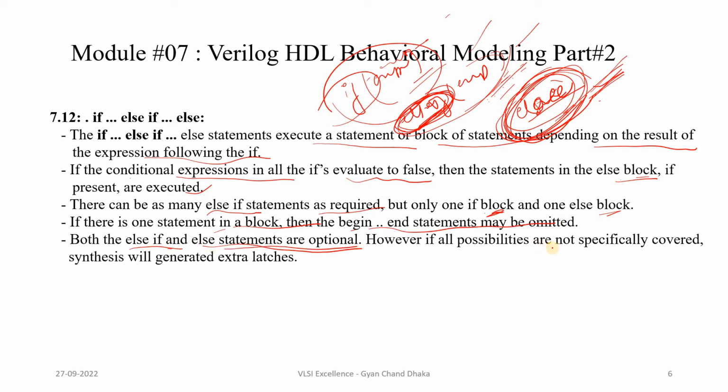However, if all possibilities are not specifically covered, synthesis will generate extra latches. The else statement is optional, and some of the else if statements can be optional too, but if those are not mentioned, then there is a possibility that the synthesis tool will generate extra latches in the design. We will see it in more detail in the next slides.